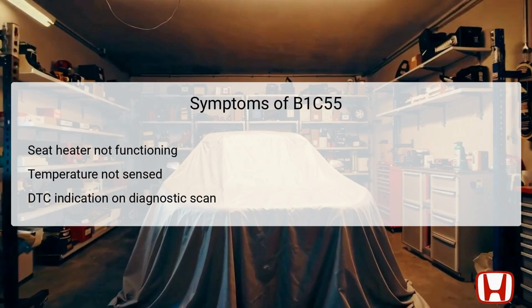Additionally, if a diagnostic scan tool, such as the Honda Diagnostic System (HDS), is used, the DTC B1C55 will be indicated, confirming the error related to the driver's heater thermistor. This can result in driver discomfort in colder weather, ultimately leading to a less enjoyable driving experience.